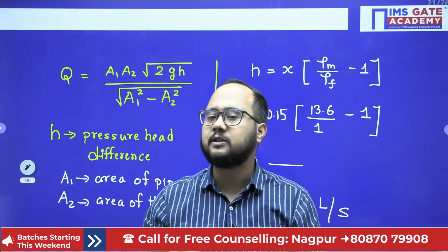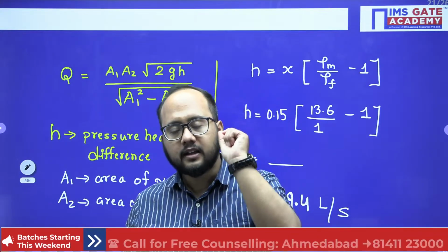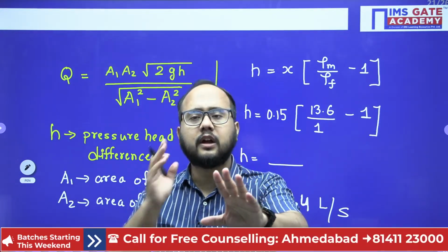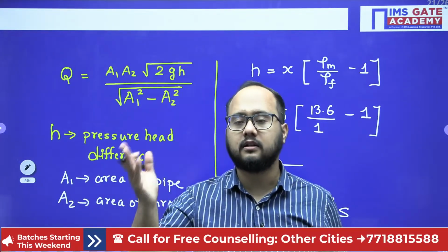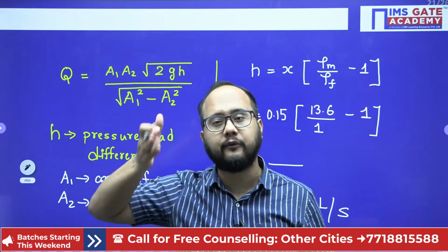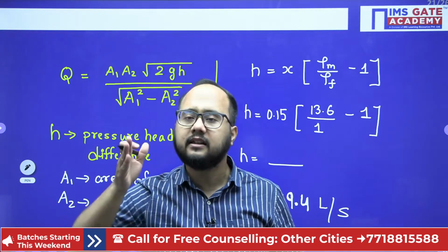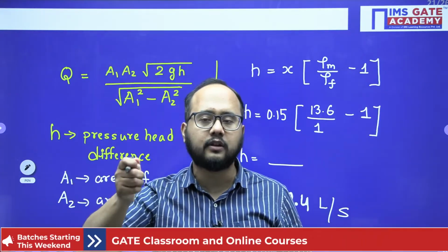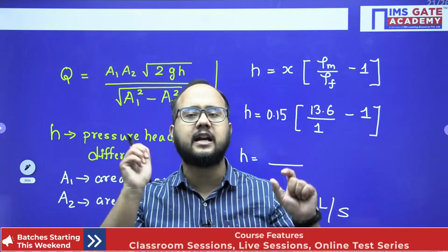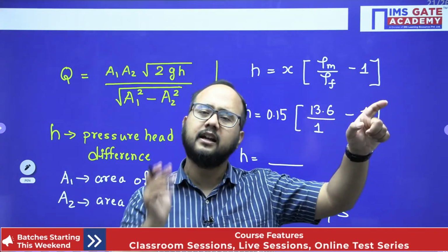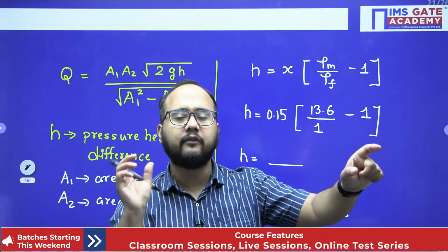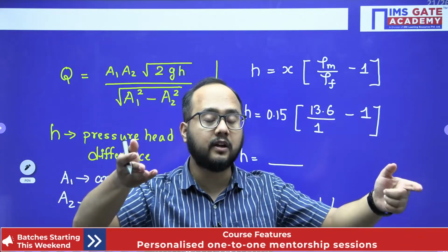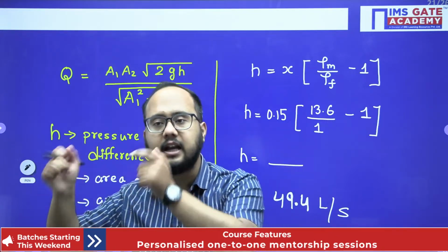So remember this point. In the pipe flow, if you simply have the Pitot tube, you cannot tell what is static pressure head and what is kinetic head. You need one more tube, which is a piezometer, from which I can calculate the static pressure head. Then after measuring that value, I will subtract the static pressure head from the total stagnation head. Whatever difference we have, that difference will give us the kinetic head.